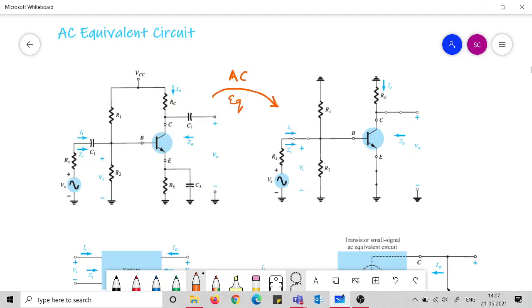We only keep in mind that there is of course a DC set point, that is a Q point, and the AC behavior is getting shown at that Q point base level, at that Q point reference level. So at those levels of your IC, IB, IE, the AC behavior is getting seen. It does not get shown on top of a zero reference level. That is what we need to keep in mind.